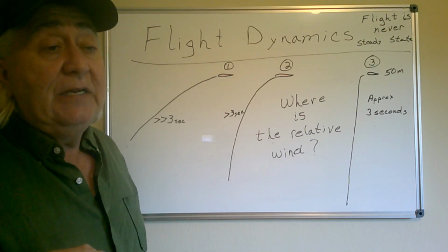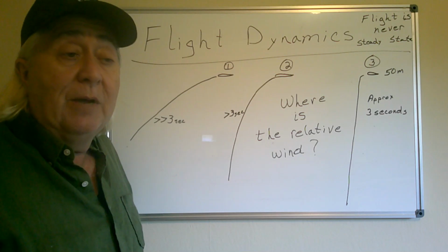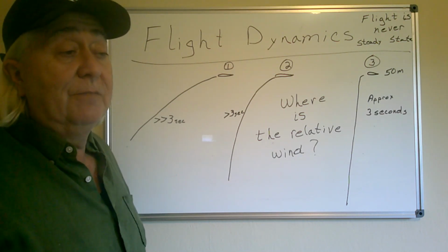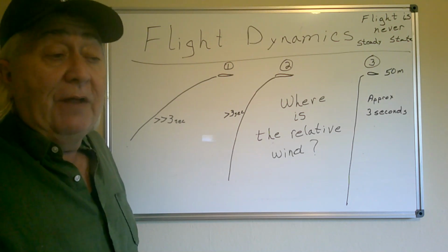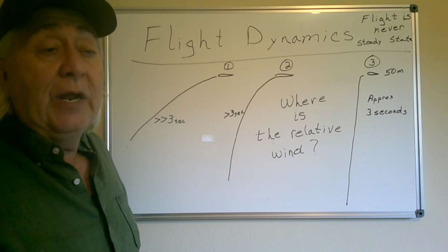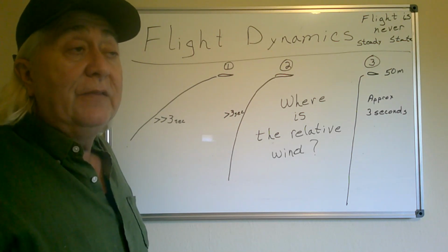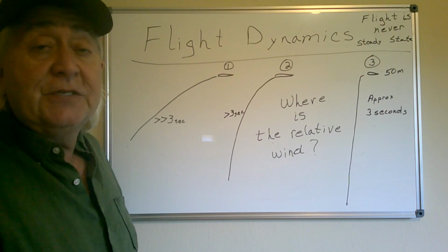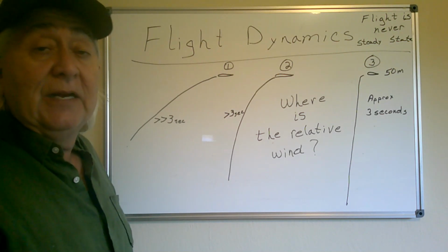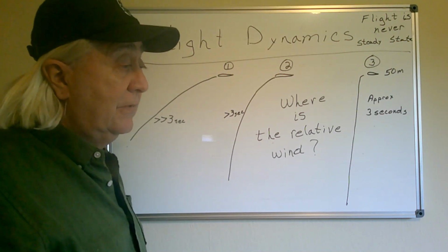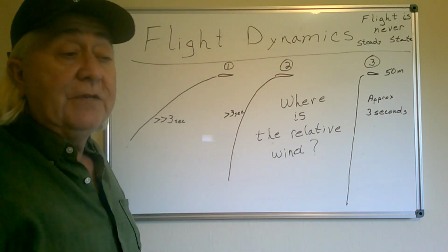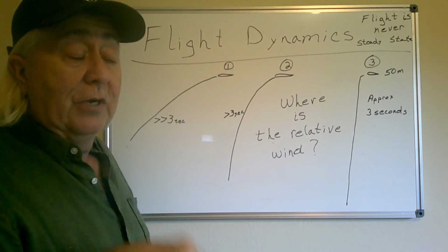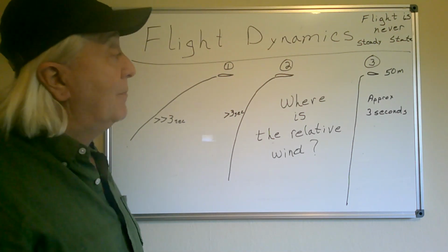I would have to say yes, because I've had problems on my glider that I've responded to in less than a second. I've had some that are more than that, but my most recent one, where I ran out of down elevator and the climb that's occurring, I was about 3 seconds into it, and I'd already tried a couple of different stick positions that were extreme, decided I didn't have enough down elevator, and I got off a toe. So more than 3 seconds is enough time to make corrections for whatever you just did that's wrong or causing a problem. And in this case, it was probably the flaps.